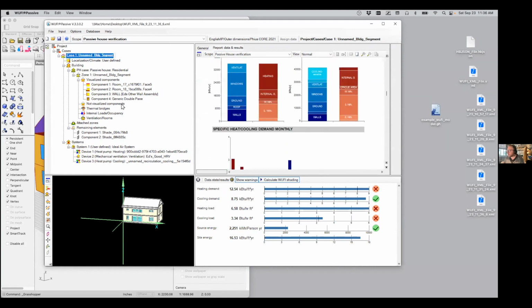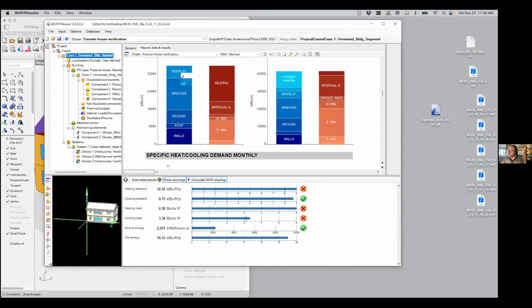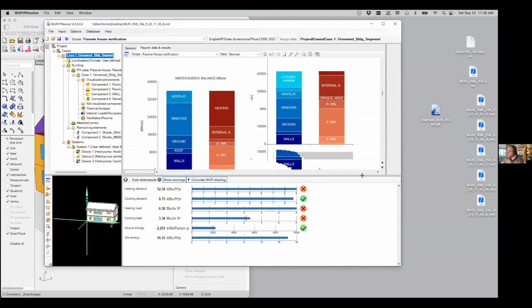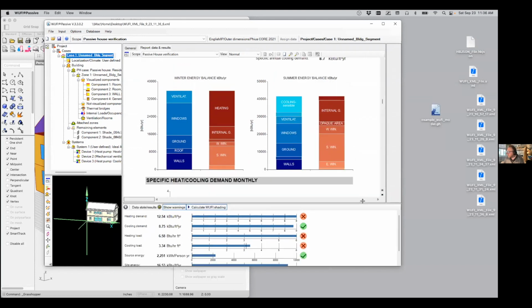heating energy balance again, now notice, having a little weird artifact thing because of the recording. I apologize, but you can see there, right? So our wall heat loss is quite low. Ground heat loss is medium. Roof heat loss is low. Ventilation heat loss is now quite a bit lower. And at this point, the biggest source of heat loss are those windows.